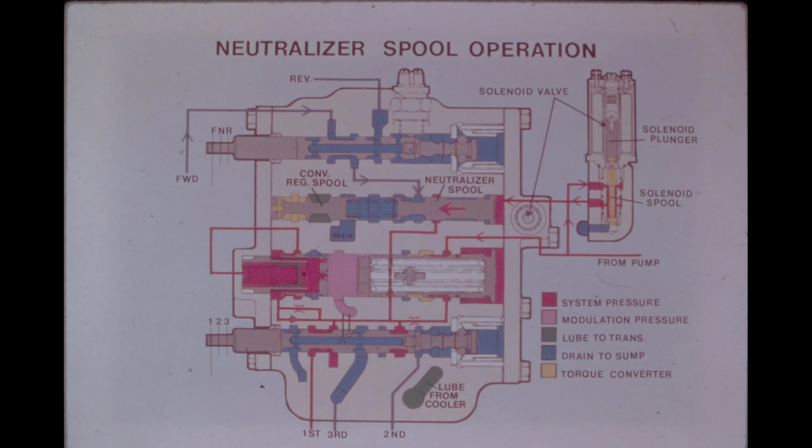If the spool remained in the applied position after the solenoid valve closed, both the forward and reverse test ports would continue to show a 0 pressure reading.